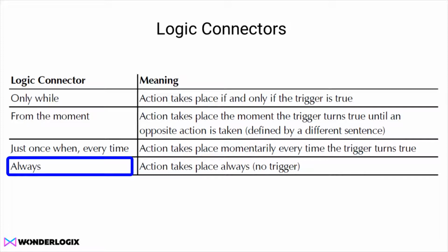So it's just always set that way. So let's see which one we need in our situation. In our case, we want to take a look at the reading and decide if filling is required based on the percentage full of the tank. Because we want to be able to turn the pump on if the level drops below 40 and turn it off once it reaches 60 or greater than 60, then we have two separate conditions.